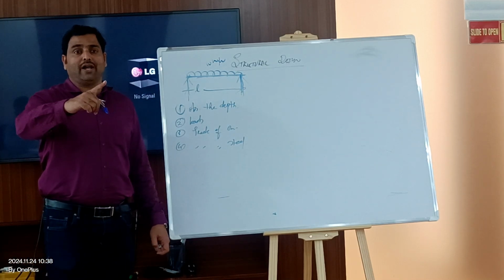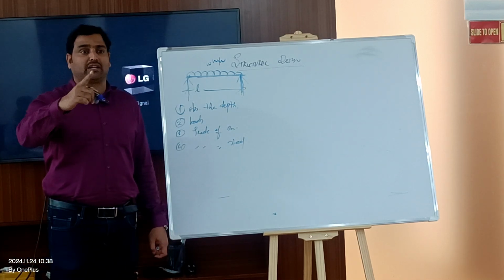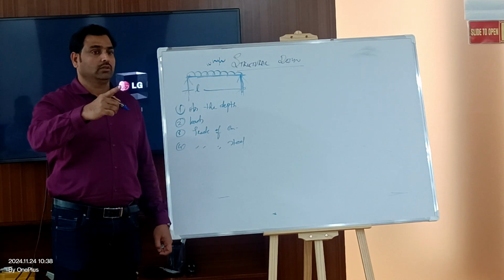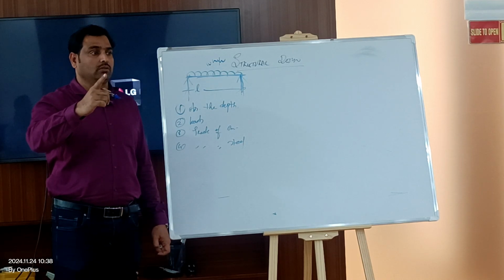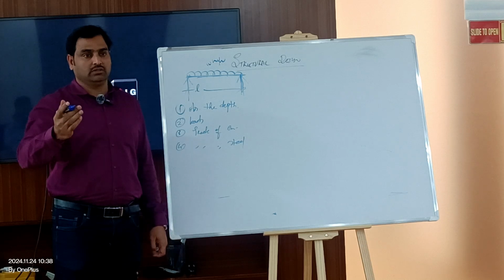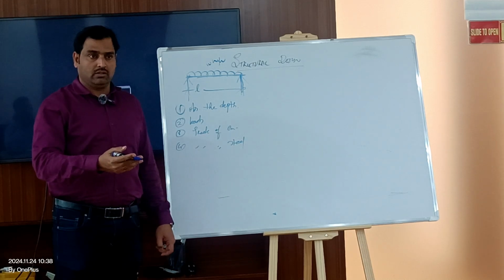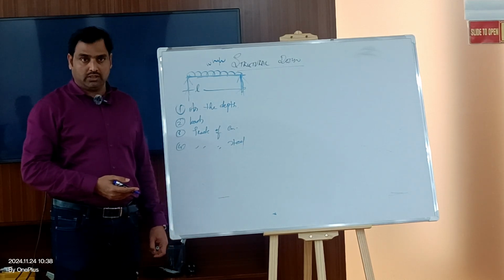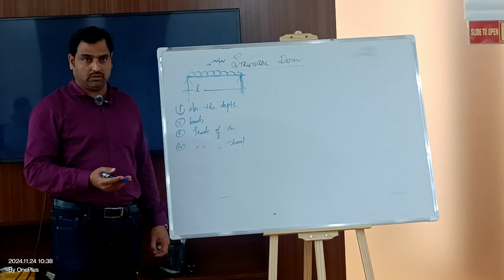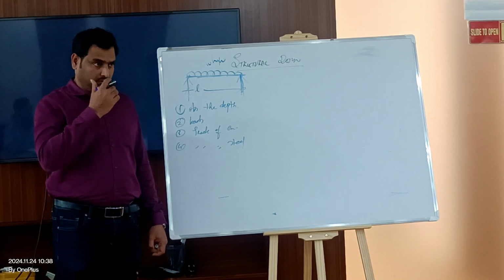If you are using a high grade of concrete, will it have any impact on the development length? Will it reduce? Will it increase? Reduce. Because if I increase the grade of concrete, definitely the development length will reduce, right? Correct.